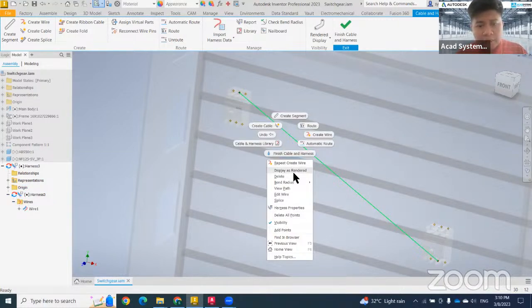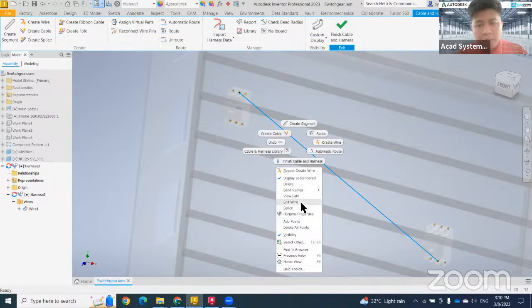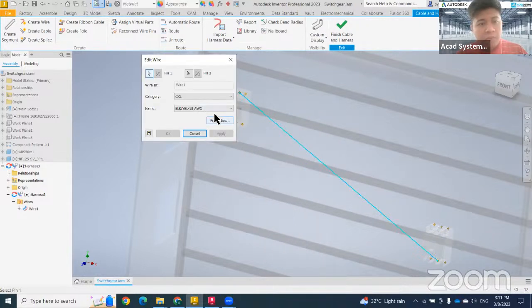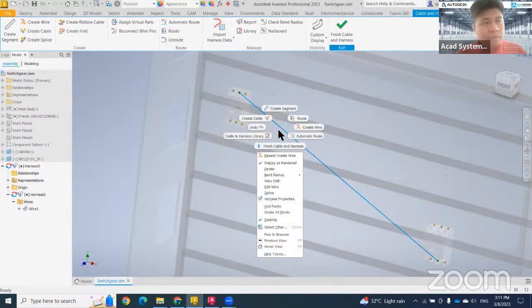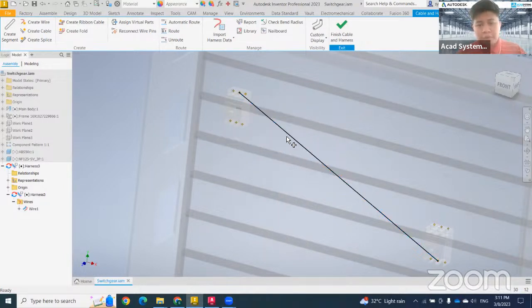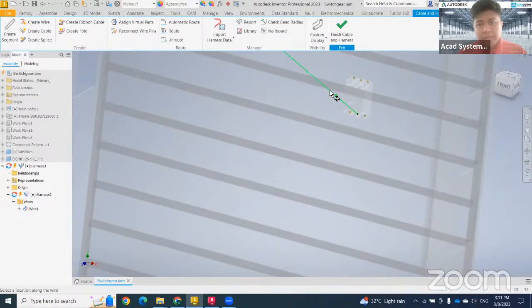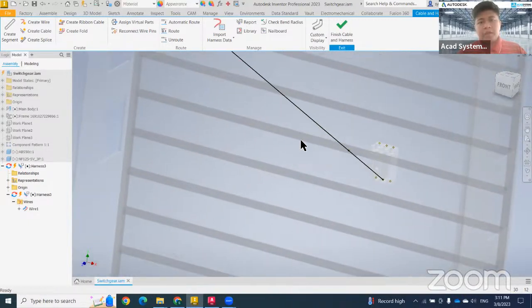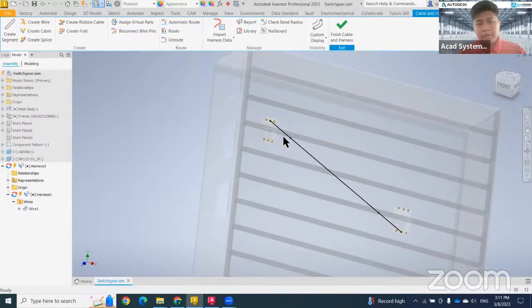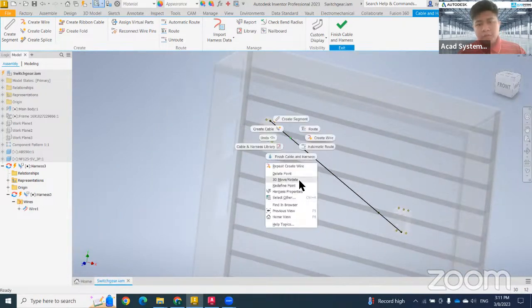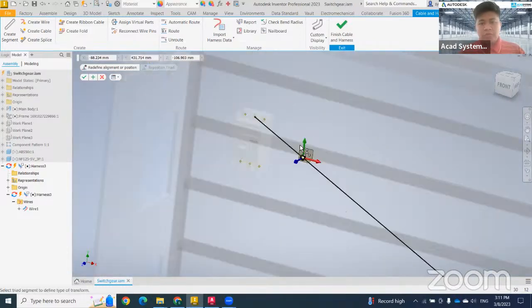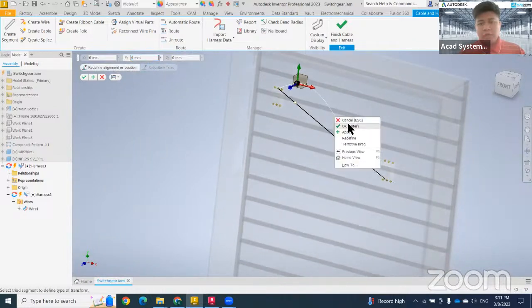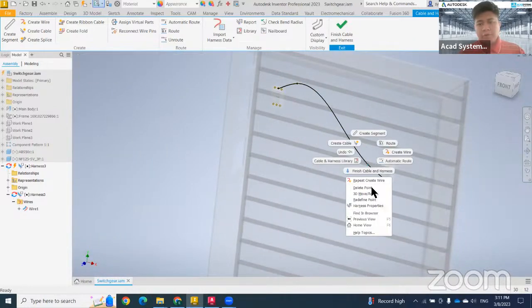Display as rendered. Another one I try is to edit the wire here. Click on this, hit add point, so first point and second point. Once these two points are added, you can right click and choose 3D move and rotate. This will give you the XYZ that you can control in your 3D parts for your wiring.